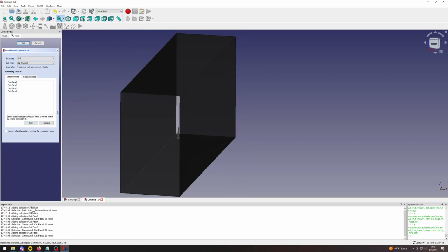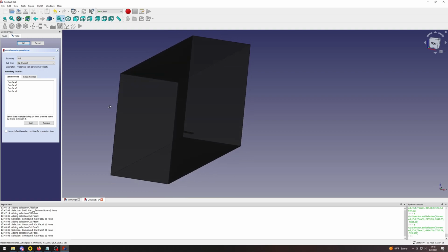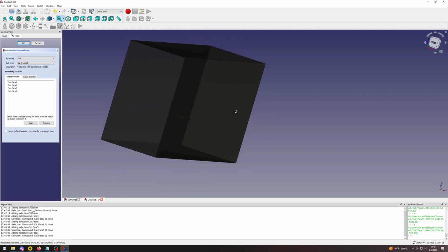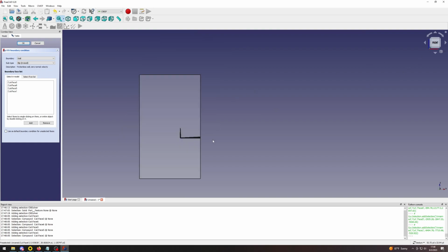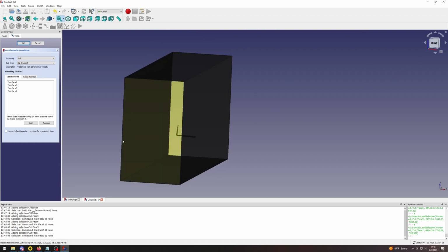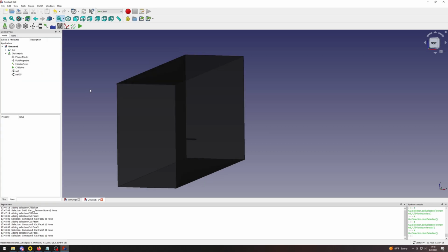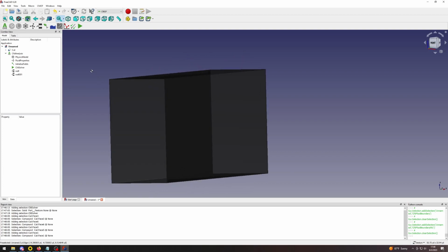So now all of those faces of our cube, and then it gets real weird when you look at it. It can really mess with your perspective, but if I go to the front view, there it is. So now we have this outside box that is now our wind tunnel, but they're slip walls. We don't want to use non-slip walls because then that would introduce more drag than what's really happening. Now we need the source of the air that's going to be blowing over this wing.